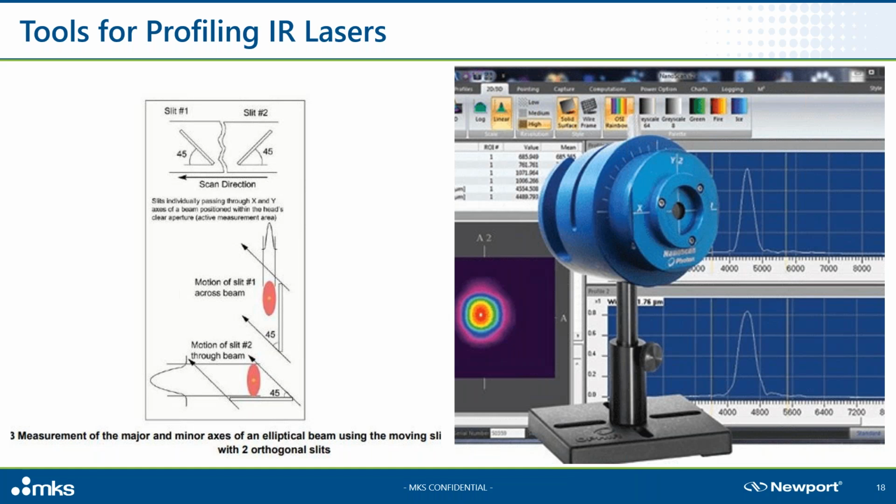results. A description of how the scanning slits work shows that while the energy is integrated in the axis of the slit, the information comes from the axis of the scan. So the scan direction dictates the information that's available, whereas the orthogonal axis of the slit integrates all the light in that axis. So instead of obtaining a true 2D map of the beam, you really have an X and a Y view. In this case, those views are put together to create a 2D image.